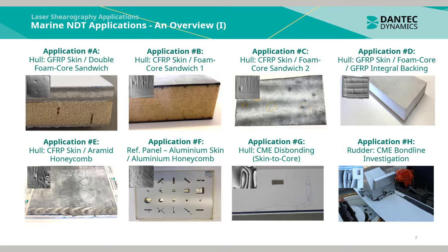In the case of laser shearography, the technology is well suited for the inspection and detection of disbonding, cracked and crushed cores, and no bond splits that can originate between the skin and the core of the material.